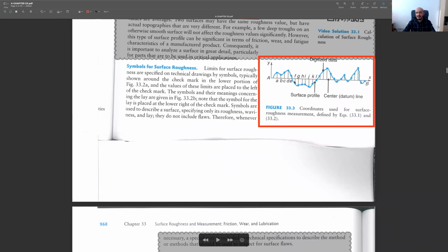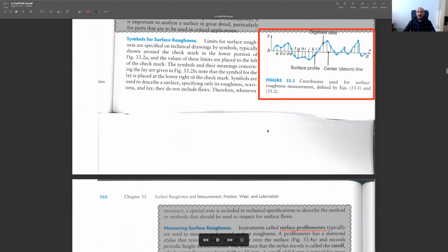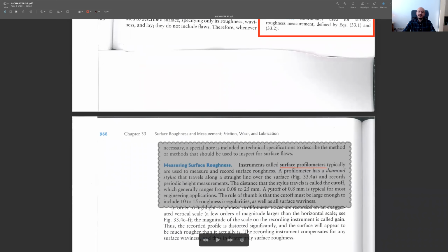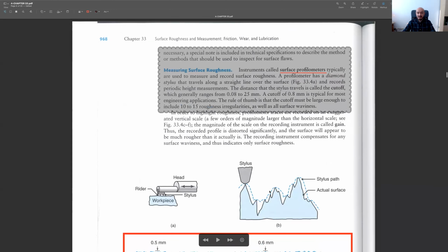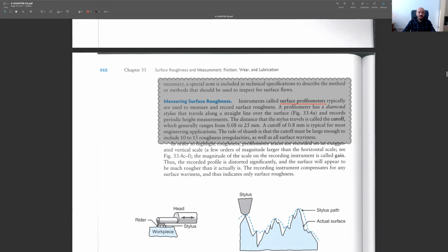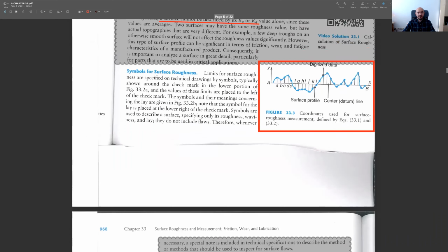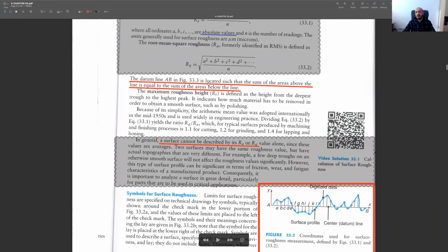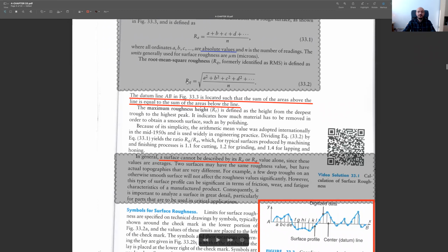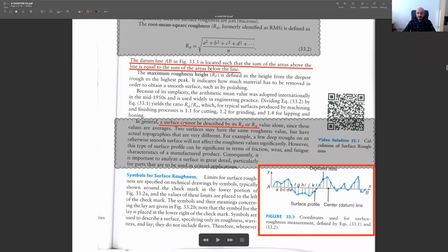It gets these measurements, and then its little computer inside performs some computations and gives you the resulting surface roughness value, mostly in terms of Ra, or if you change it, it can even give you the Rq value, the RMS value of your surface.